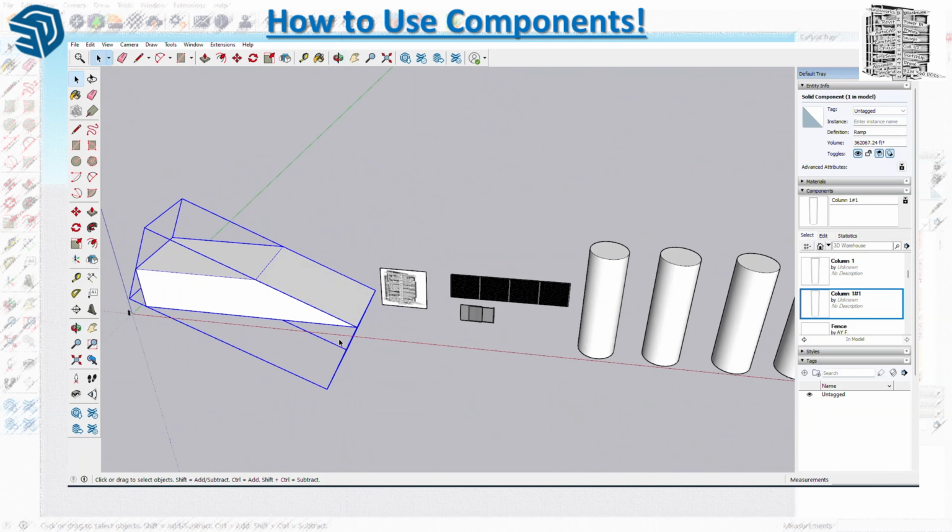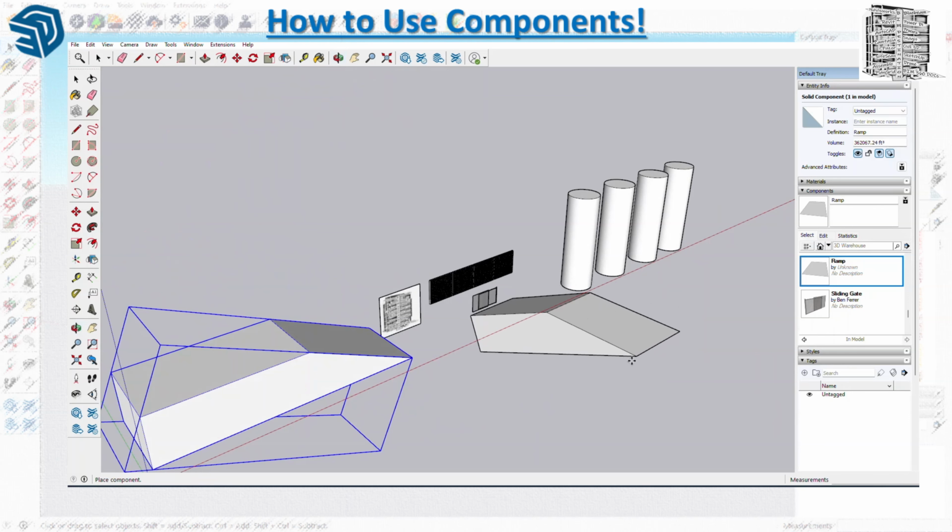So this is really, really helpful that I want you to understand. And then another note, you see where my move button is? It basically snaps to a location that is my 0,0,0, like the origin. If you remember, I put my X, Y, and Z at this corner. That's why when it comes in, this is going to be my 0,0,0.